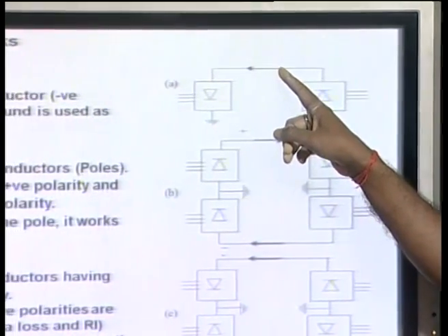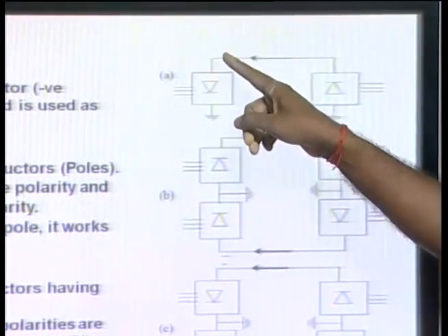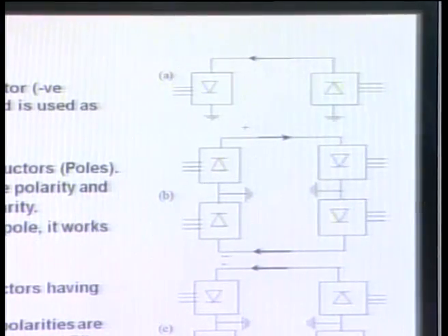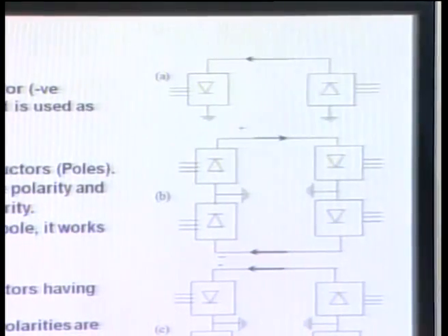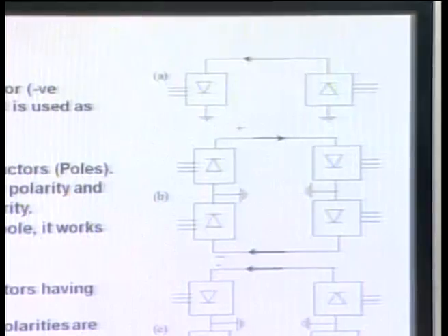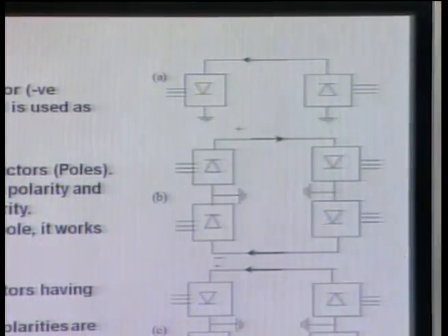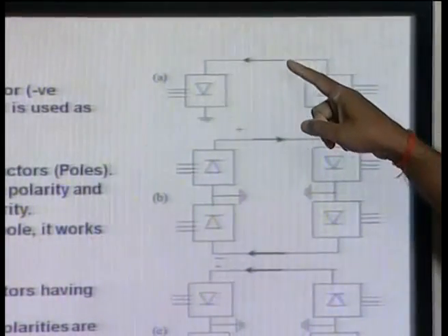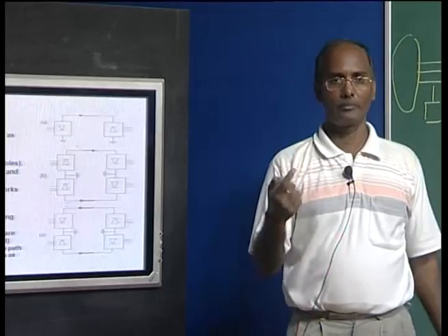and that is why this operates at negative polarity. The major problem here is that if there is any problem in this link, either in the converter or in the DC system, you have to stop the power flow completely, and power cannot flow from either end. So monopolar means you have only one pole, meaning one wire, and the ground is used as the return.